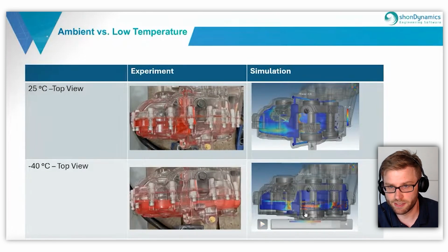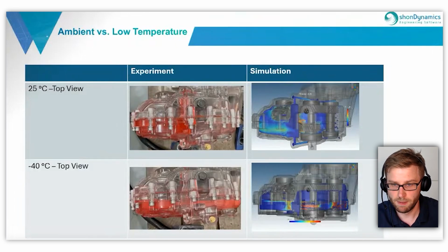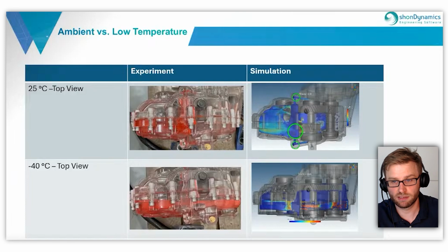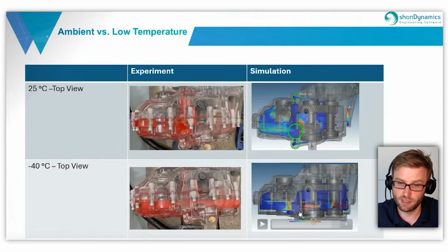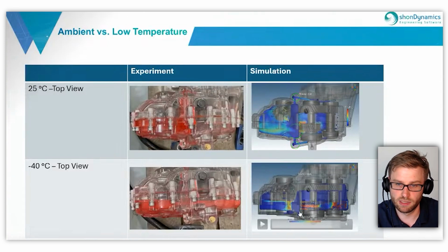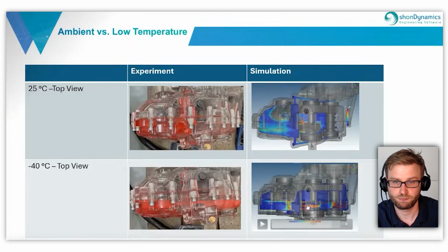The reason for that is that at the beginning of the simulation we have all the liquid at the bottom of the gearbox, and then the lubricant gets distributed around the gearbox, and then there's not enough fluid left to be carried by the output gear on top of the gearbox and into the pool.